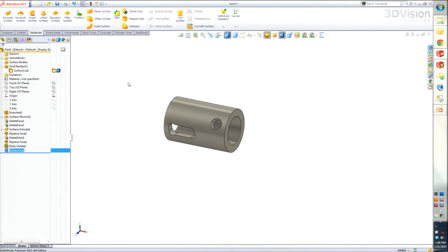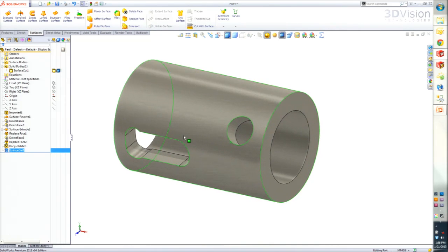Planes extend infinitely in all directions. Surfaces are confined to the size of their surface. So that's why the cut with surface can sometimes be more beneficial than just drawing an extrude cut or a line and extrude cutting everything to the right or left of it. It's more confined. Now here's another scenario where the replace face command comes in handy.